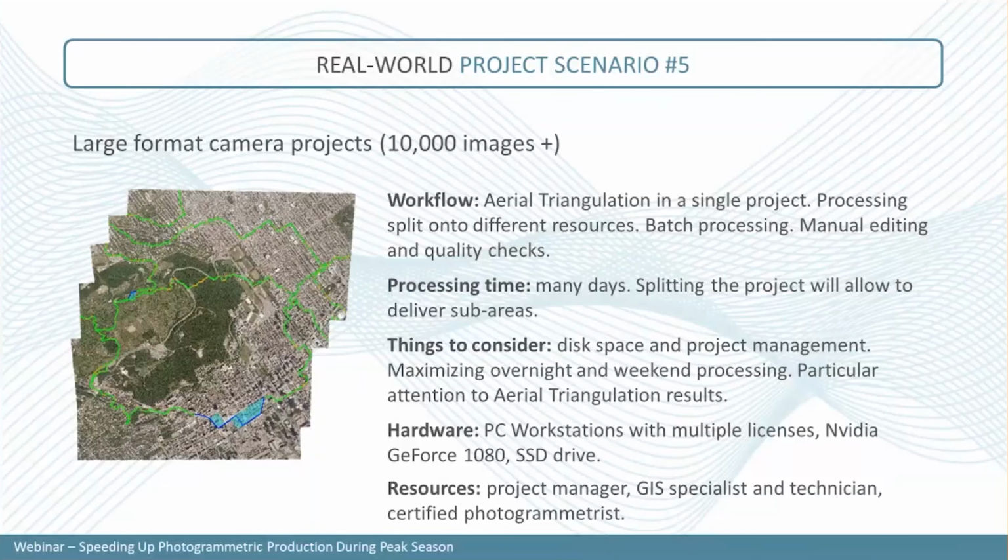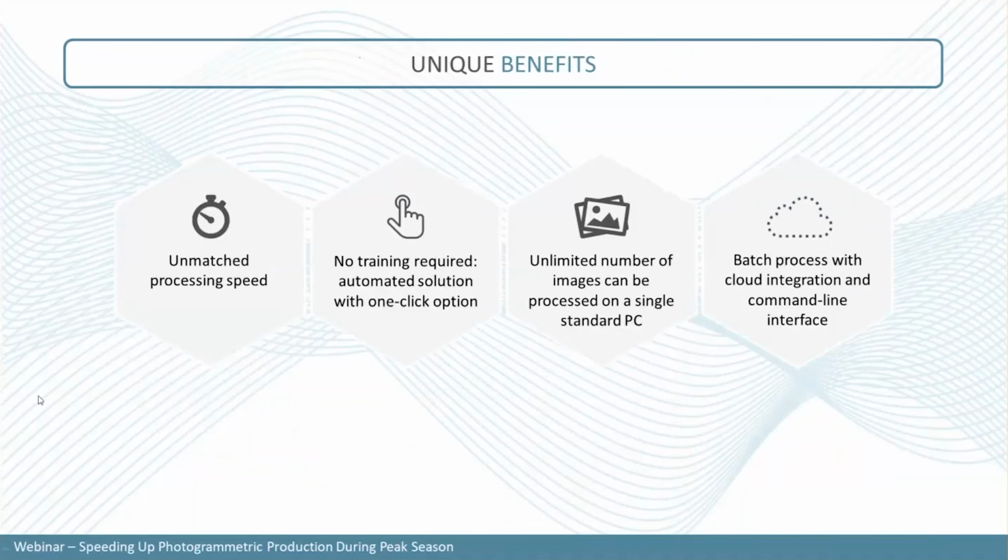Also, if for any instance you have LiDAR for such a project, you can directly import LiDAR in your workflow, and it should reduce the amount of time you need for your project, since you can use the elevation data from the LiDAR to derive the ortho photos and then colorize your LiDAR point cloud.